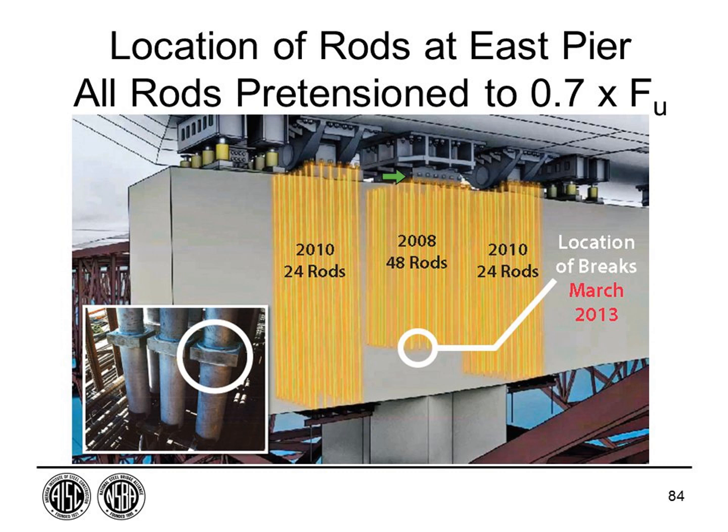These are the rods. In order to build this bridge, they actually had to build another bridge to support it. You see the truss here. Because this is not a normal suspension bridge. It's a self-anchored suspension bridge, so you can't hang the deck from the main cables. So they were supporting the bridge as they were building it on another truss underneath and holding it up.